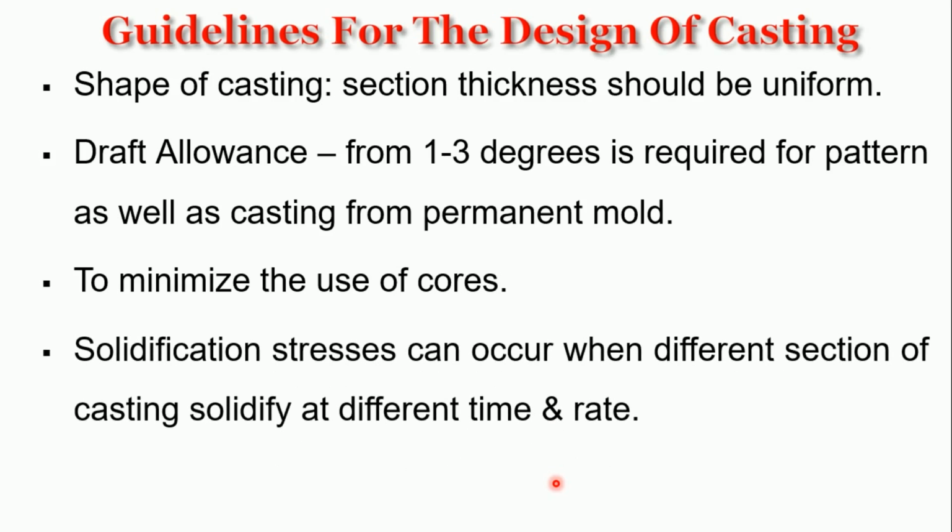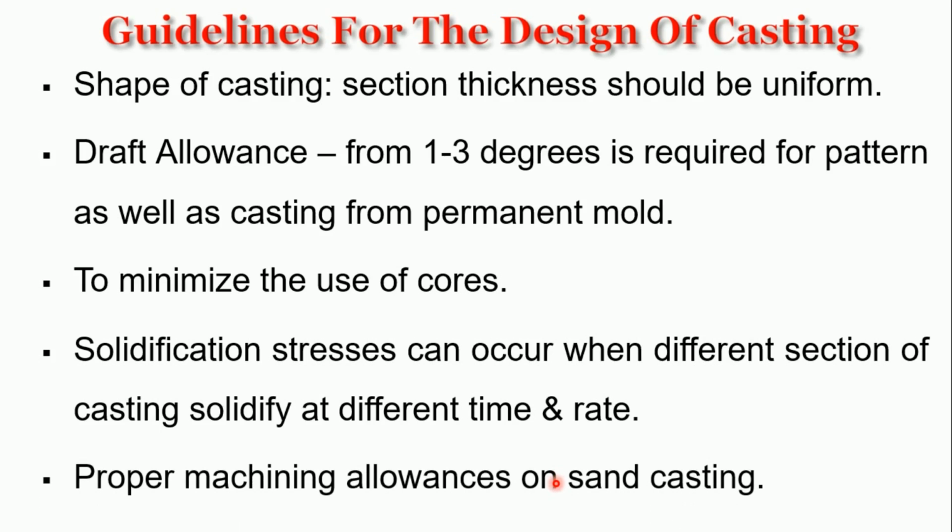Solidification stresses can occur when different sections of the casting solidify at different times and rates, and a proper machining allowance on sand castings is needed. These are some short guidelines for the design of castings. Generally we use geometric simplicity and avoid unnecessary complexity, which simplifies mold making, reduces the need for cores, and improves the strength of the casting.